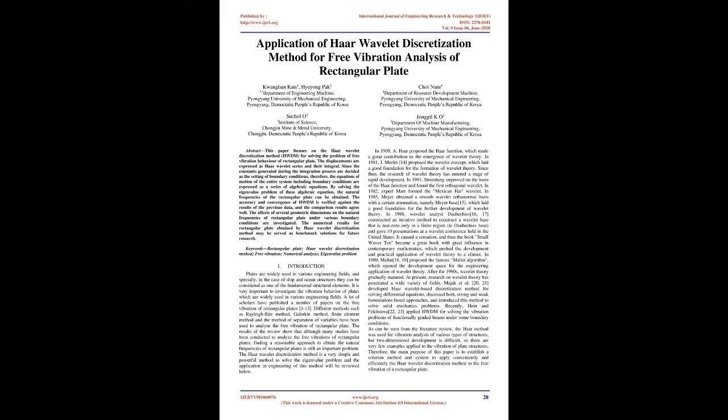rectangular plate. The displacements are expressed as Haar Wavelet series and their integral. Since the constants generated during the integration process are decided by the setting of boundary conditions, the equations of motion of the entire system including boundary conditions are expressed as a series of algebraic equations. By solving the eigenvalue problem of these algebraic equations, the natural frequencies of the rectangular plate can be obtained.